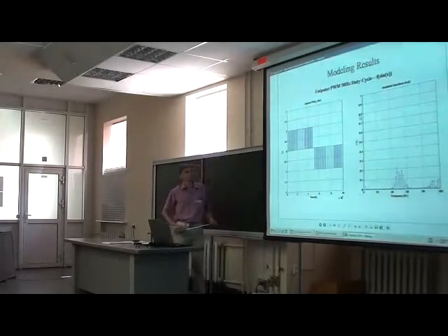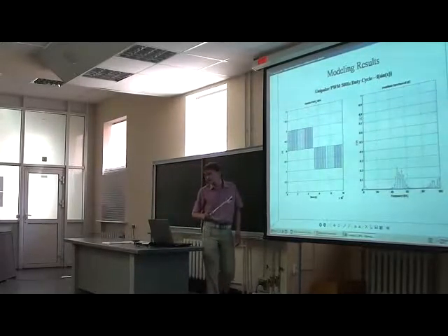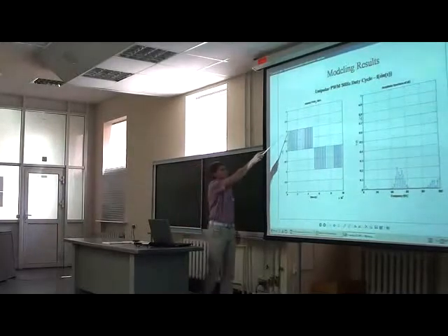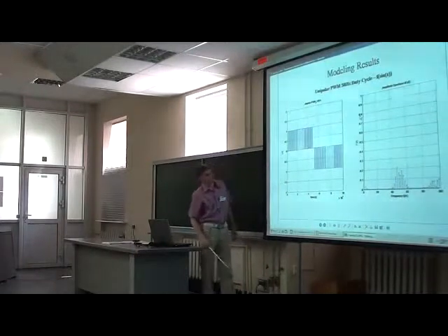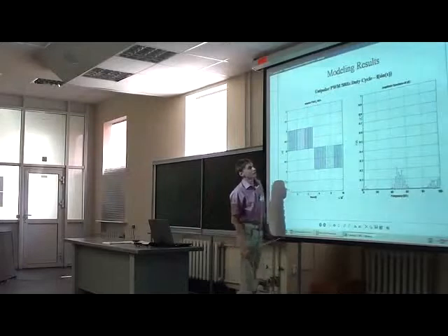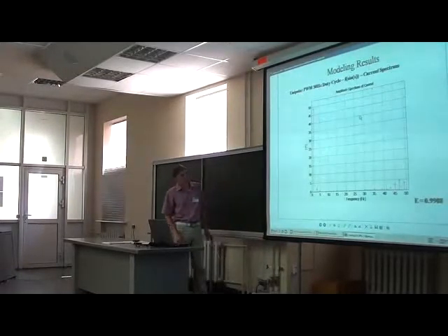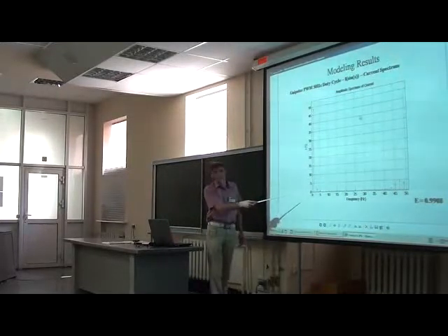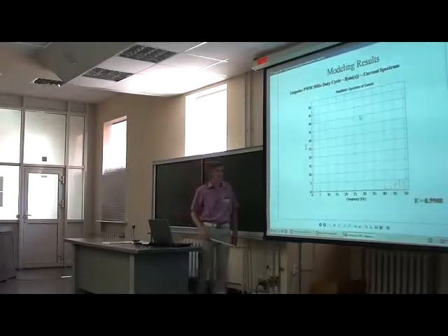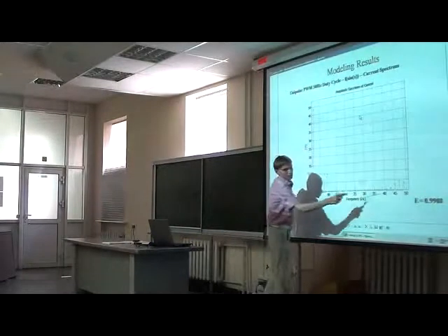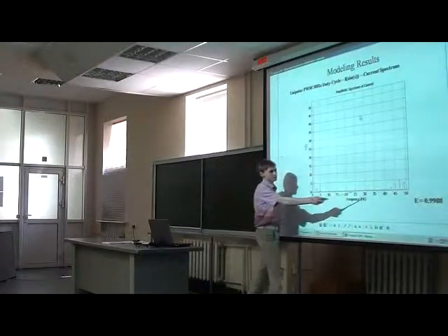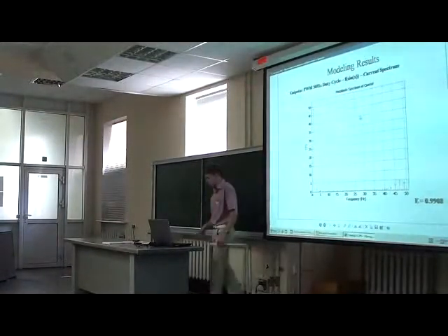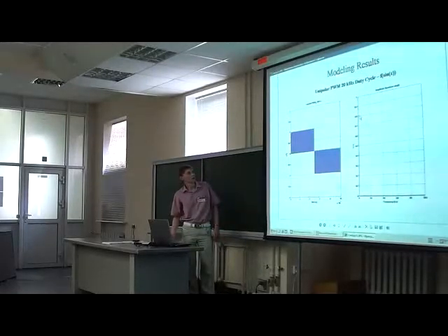Then we can simulate the unipolar PWM with duty cycle. We change the duty cycle according to a sine wave. You can see that here. The duty cycle of impulses is changing. This is the frequency domain of these impulses. Current. The first harmonic is here more than in the previous example, but we here have also a negative influence of high harmonics. But the energy efficiency is larger.